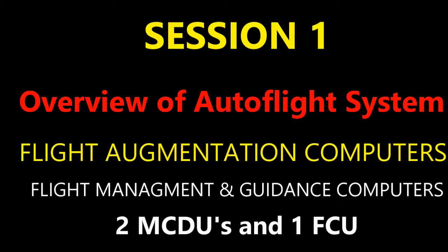But here we're talking about the typical colors that you might find on the messages that show up, which will be red, amber, or white. Obviously amber is caution, red is, hey, this is very important, and white is just letting you know that something's here. The priority is with red, meaning there's something that really needs your attention right now. Amber is not so bad. This is your second priority.